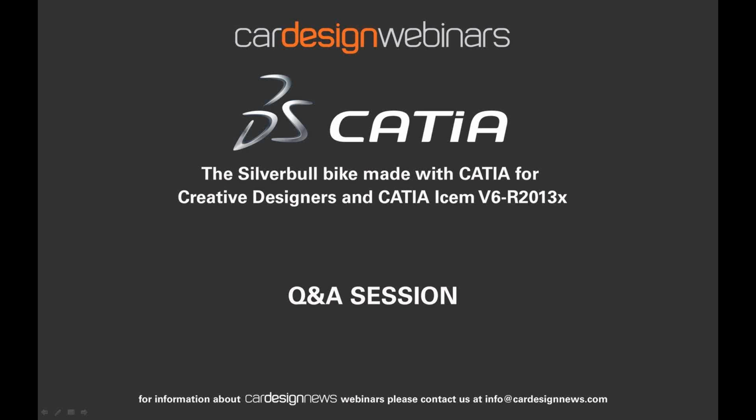There is another question. Is there a way to do patterns in Imagine and Shape? Pierre, if you want to answer. Yeah, so in Imagine and Shape, you're able to create what we call instances. So you're able to do some copies of a subdivision, and when you modify the mother subdivision, the children will be updated at the same time. So you can do patterns, and you can keep the associativity in order to be able to update them.